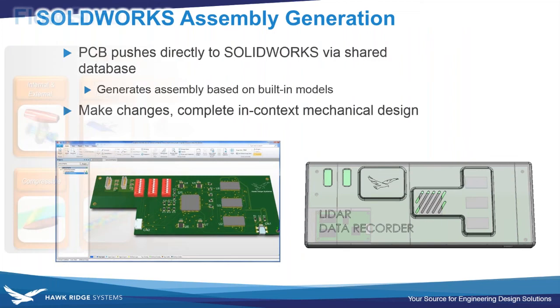Something that is probably a little more typical for what you see would be like in the bottom right image there. Once I bring this board into SOLIDWORKS, which of course you can see the fully detailed version of on the left, for example, those RAM components, the memory chips on the right-hand side of the board, they just become simple blocks. Again, every company's different, but this is what we usually see. This was typical. So how do we account for those details when we've already simplified the model in SOLIDWORKS?